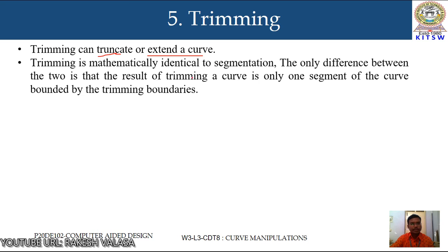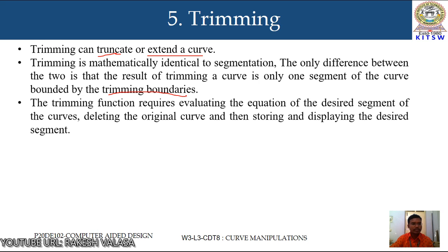The only difference between the two is that the result of trimming a curve is only one segment of the curve bounded by trimming boundaries. The trimming function requires evaluating the equation of the desired segment of the curves, deleting the original curve, and then storing and displaying the desired segments.